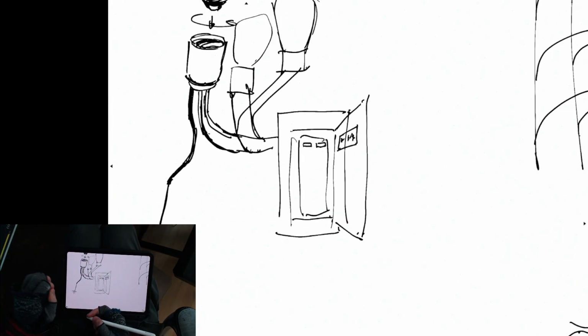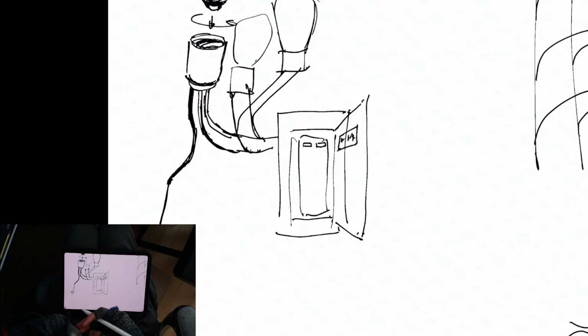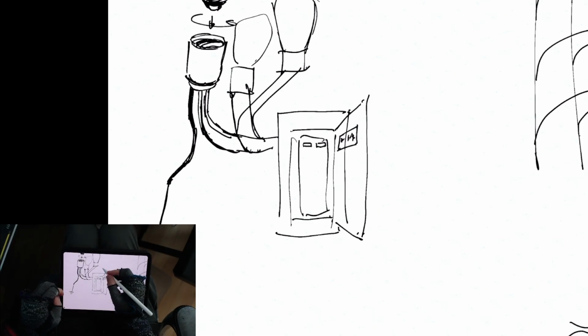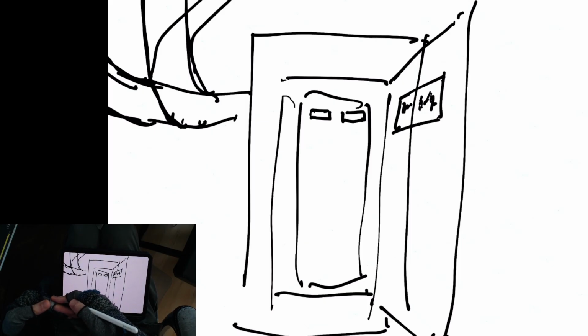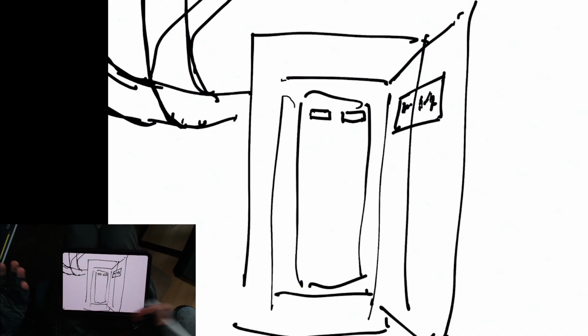The thing is that amperage draw is the amount of electrical flow, the amount of current flowing, the amount of power or energy being drawn. This is why if you put too many bulbs in parallel, the load on your circuit breaker, which is a little piece of bimetallic resistive metal, gets hotter and hotter. When it's overloaded and too hot, it breaks the connection to avoid causing an electrical fire. You don't want too much heat being generated. That's what causes electrical fires.